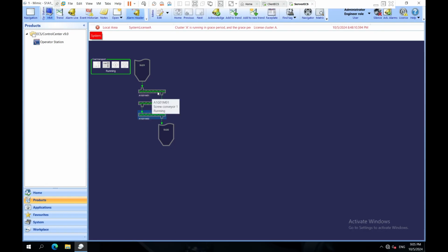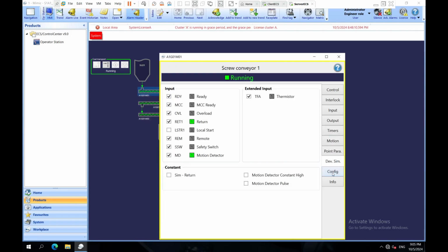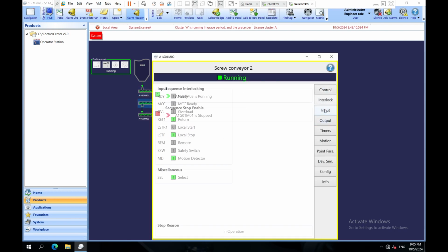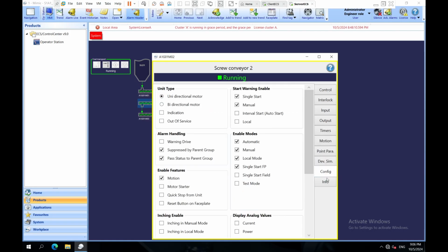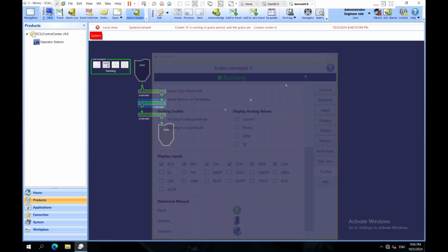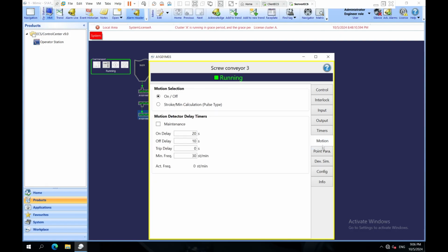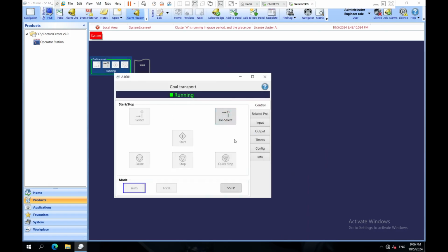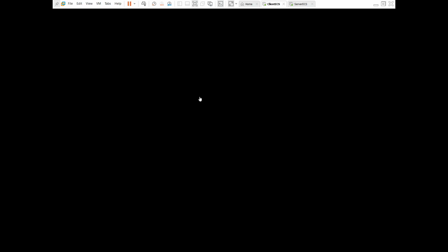However, it's important to note that these changes only affect the actual values in the data block of the simulated controller. This means that if the controller is running in simulation mode, the changes won't be automatically saved in the offline data blocks. When you disable the simulation and reload the controller, the offline blocks, which haven't been updated, will be loaded into the controller, and this could result in losing the configured settings. To prevent this, it's a good practice to manually copy the data blocks from online to offline once your configuration is finalized. To perform this operation, follow these steps.